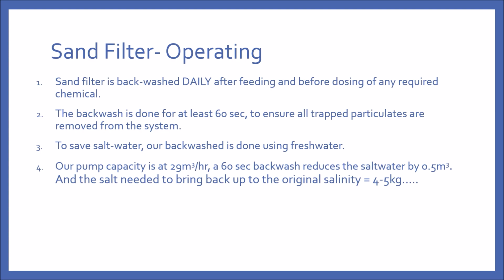Suspended solids that are trapped inside the sand filter have to be removed from the system, and the removal method is to execute what we call backwashing. On a daily basis, we have to backwash at least once to ensure that the particulates that are trapped do not start decomposing in the system and further deteriorating your water supply. We do a backwash of at least 60 seconds to ensure all trapped particulates are removed.